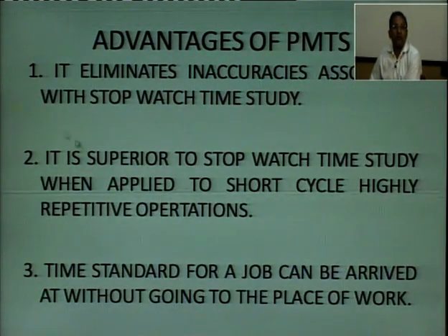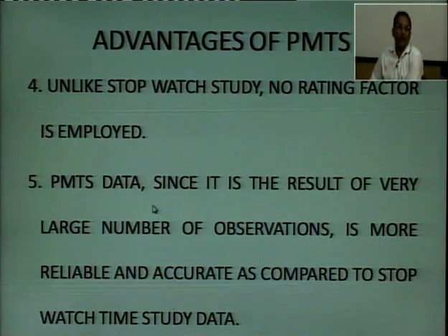The advantages of the PMTS. Number 1, it eliminates inaccuracies associated with stopwatch time study. Number 2, it is superior to stopwatch time study when applied to short cycle, highly repetitive operations. Number 3, time standard for a job can be arrived at without going to the place of work. Number 4, unlike stopwatch study, no rating factor is employed.